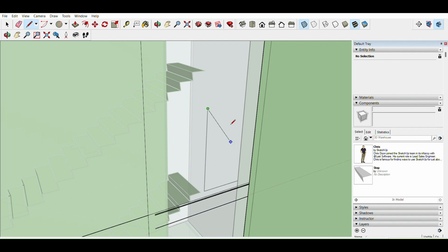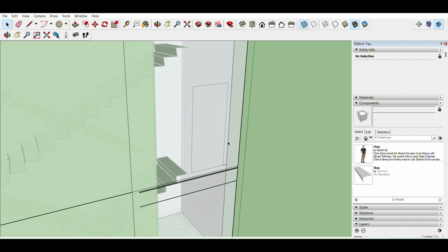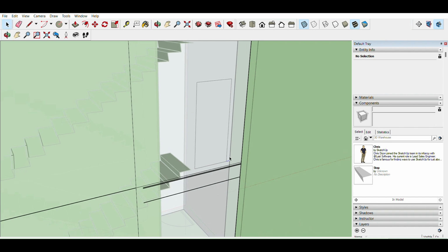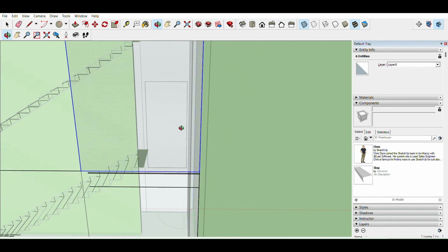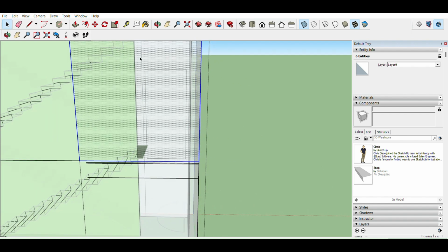Door itself is 6'8", but you need to have that 1 inch underneath. So there we go. I mean, generally speaking, for construction, if you actually want to have the proper framing numbers in there. So that is going to be a door. Why did I do it on the inside? It seemed easier at the time.